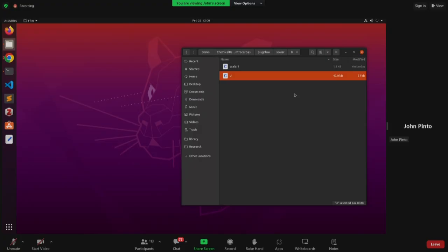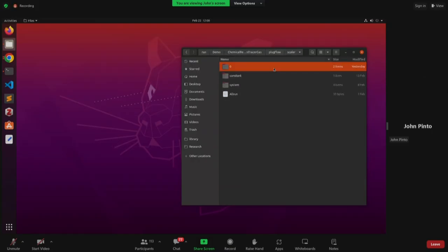So understand, to do a scalar simulation, you have to do two simulations. One is for the flow, wherein you get the flow established. Then you solve how that flow affects the scalar, or how the scalar moves in the flow. This is done to identify certain features, as sir said. Is there any mixing, right? If I inject scalar at one end, whether it will go down or not. All those things can be studied with this. So my U is an initial condition, so that has to be copied.